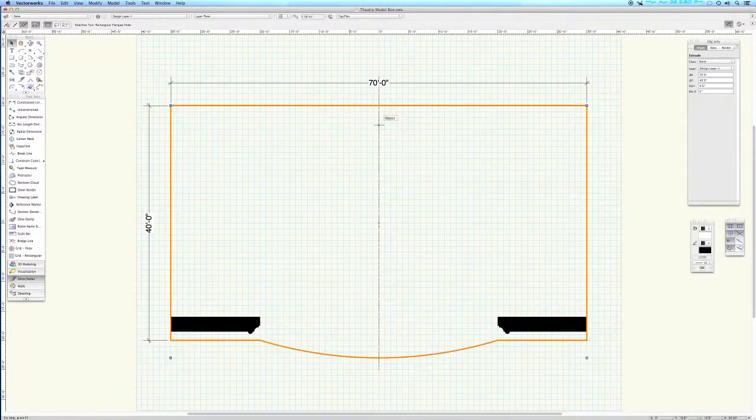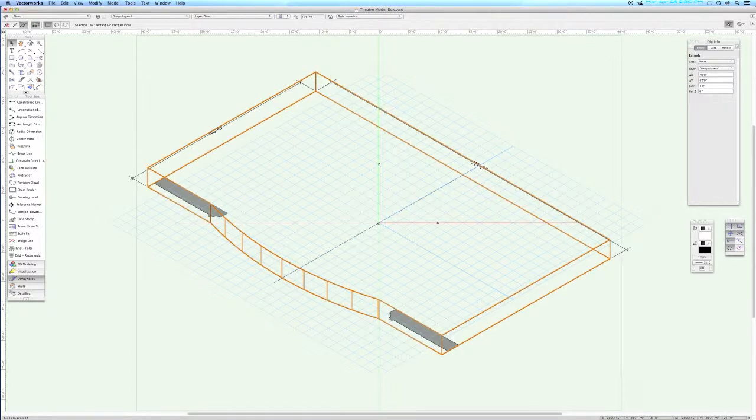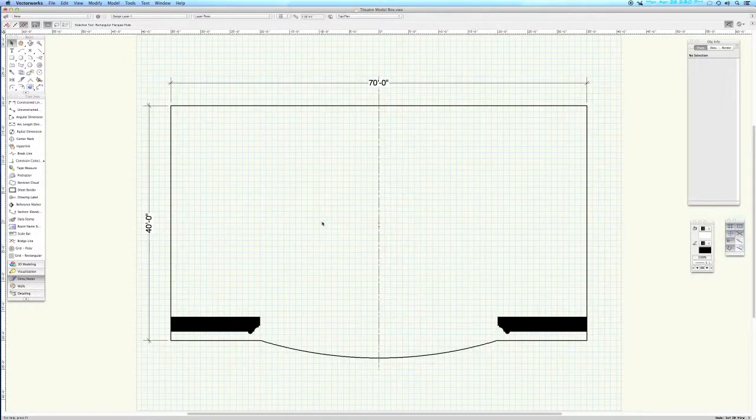Now when I hit the 3 key on the numerical keypad, it's going to show me the right front isometric. Now you can see that this has dimension. But when I grew the dimension, it grew vertically in the plus direction on the z-axis. And I actually want to make our stage floor be 0, 0. So I'm going to undo and undo.